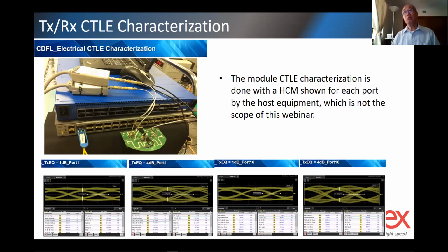It doesn't mean too much. Basically, you change the shape, the rise time and fall time. In practical terms, you change the rise time or the fall time in order to generate this MSA compliance trace response.